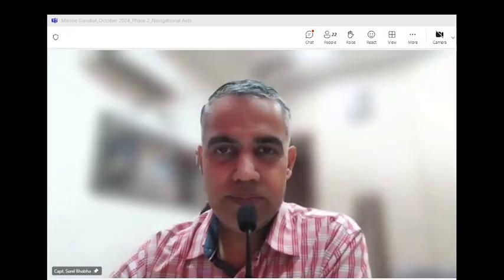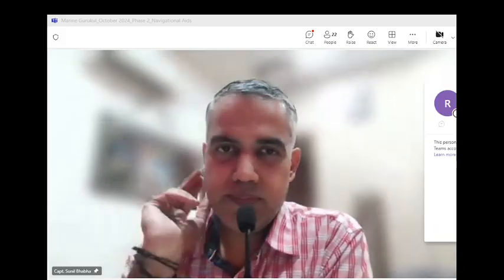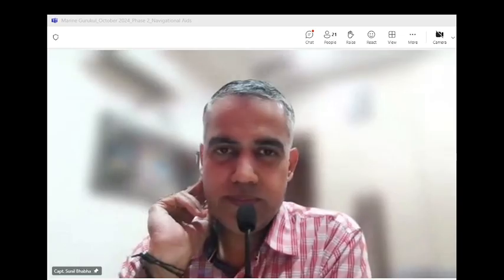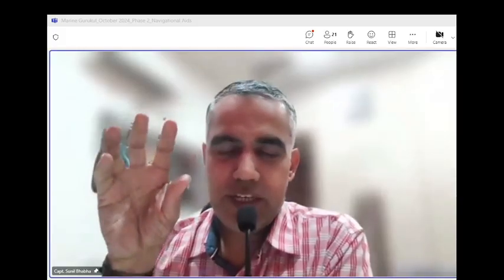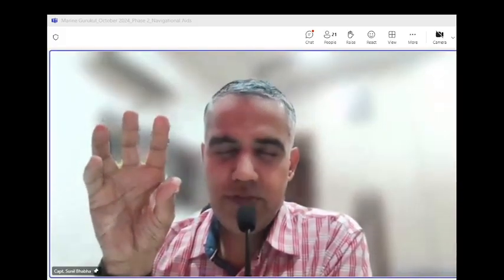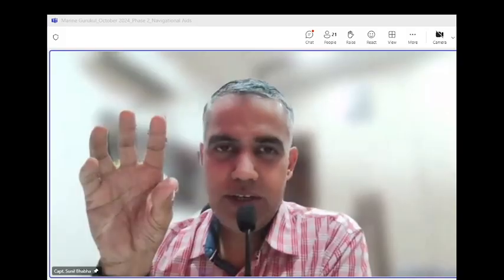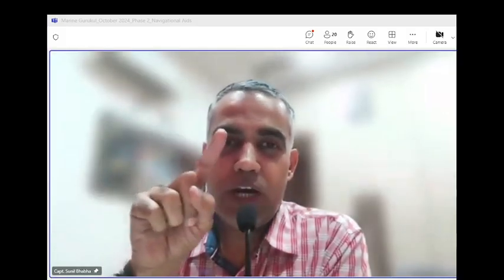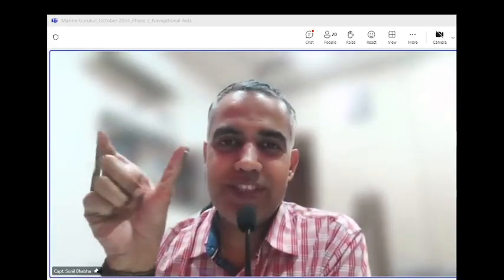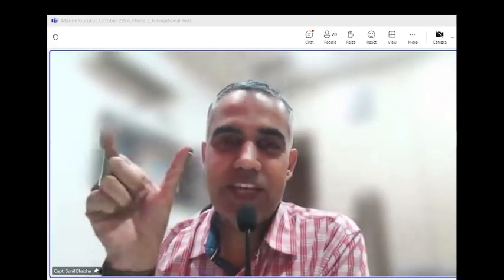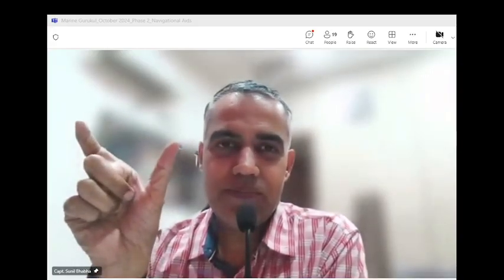Go ahead, beta. So that VRM, you set it for how many miles, sir? Setting of the VRM to identify the wheel over line. It will be equal to R into 1 minus cos theta plus F sin theta. The distance that came, beta, that will be the VRM setting. Okay, sir.